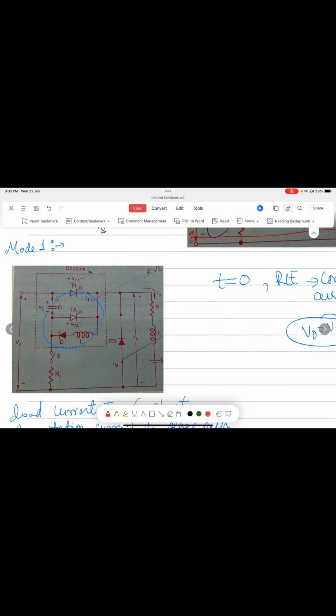So how can we charge this capacitor initially? There are two methods to charge this. The first method is that if we just turn on this switch, the supply voltage starts flowing through the capacitor and has a return path through this resistor to the back path. So the capacitor will get charged. When the capacitor is charged to the supply voltage, the charging current is equal to 0. That I have already discussed in various classes. So this capacitor gets charged.